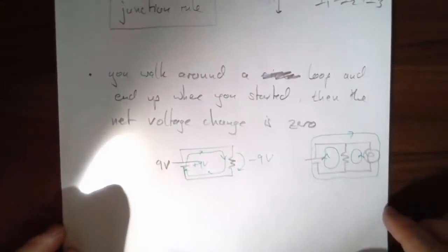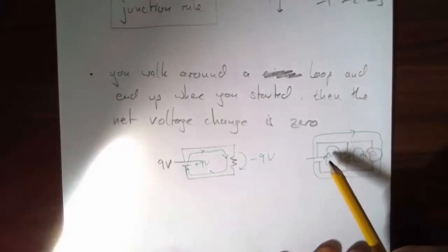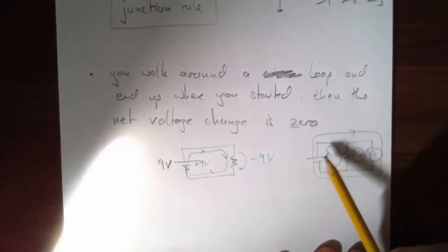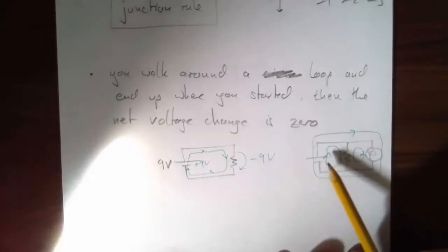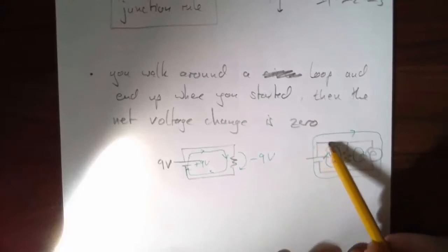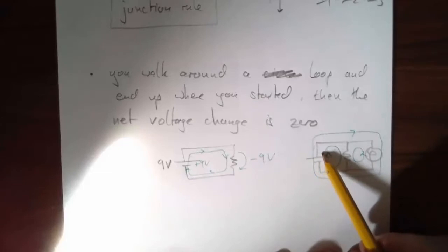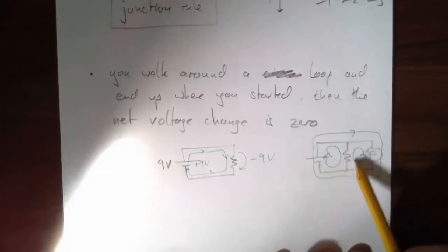You have to be very careful in the application to get the signs of the voltage change right. I do an example of this in the homework preview, where I analyze problem 52 from chapter 28. But the rule of thumb is that if you go with the current, then batteries will take you up, resistors and capacitors will take you down.